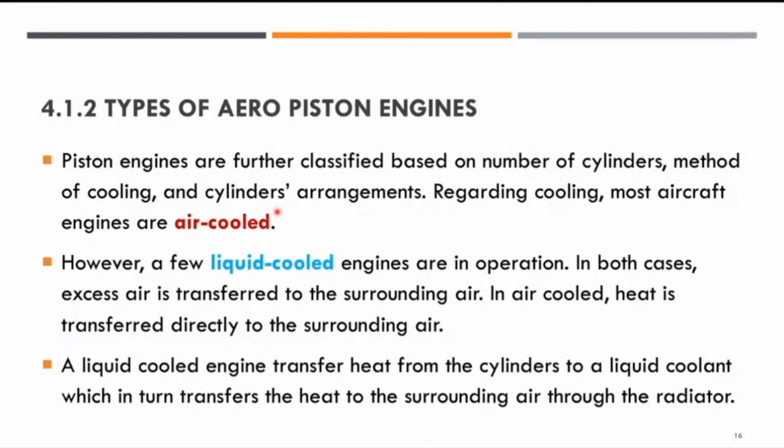the cylinder arrangement. For example, regarding cooling, most piston engine aircraft are air cooled, right? This is to make sure that the engine is working at the right condition. However, there are also a few liquid cooled engines in operation. Of course, when you say liquid cooled, it means that you have to carry the coolant to cool the engine, compared to air cooled where we can just use the atmospheric condition.